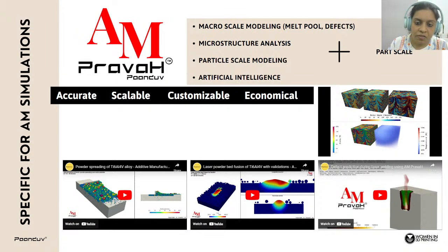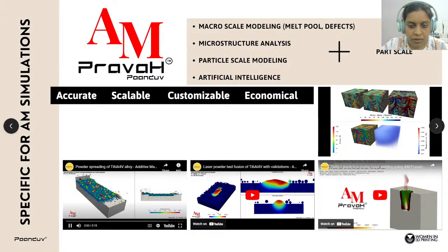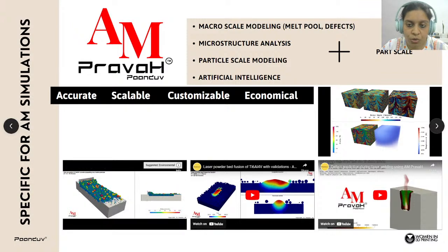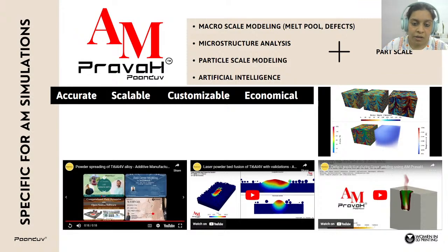Let me just elaborate on how it performs, because I have some sequential animations so that you will understand the LPBF more carefully. This is the first animation, which will show you the particle analysis, particle scale modeling. There is a scraper, or you can say spreader, which will spread the particles uniformly in the bed over the substrate. It has removed all the unwanted, larger particles which are not giving a uniform spreading of the